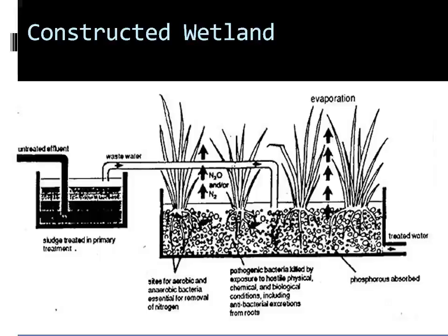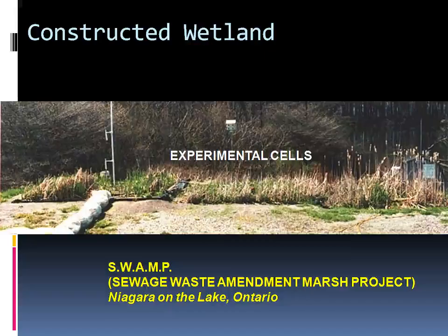Thereafter, the step is sediment removal. Sewage, even after removal of grit, still has suspended solids. These will settle out if the speed of sewage flow is reduced. This is accomplished in a sedimentation tank. The suspended solids settle out and a solid mass called raw sludge is collected for disposal.